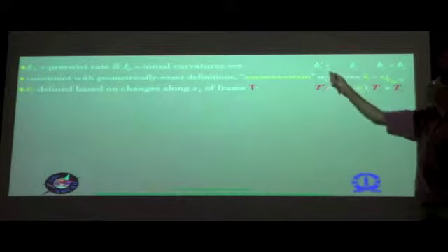So you would have a very similar definition compared to what you have in the undeformed configuration. Now in the deformed configuration, instead of the small b's, you now have the big T's, and instead of the small k, you have the big K, which is now the small k plus the kappa. And this kappa is no longer the same as before, but the kappa bar, which is under the condition that gamma 1 alpha equals 0. So that is basically what you have here.